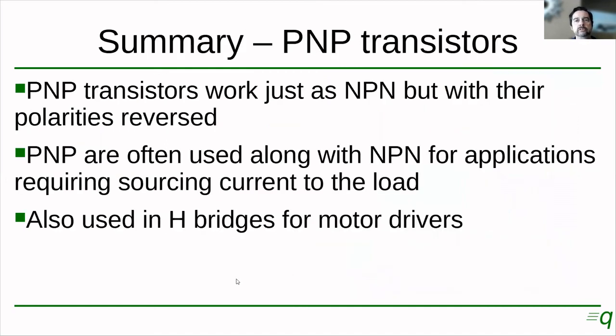So let's do a quick review of what we saw today, right? We studied PNP transistors, and they work just as NPN, but with their polarities reversed. And PNP transistors are often used along with NPN for applications requiring sourcing current to the load. They're also used in H bridges for motor drivers.